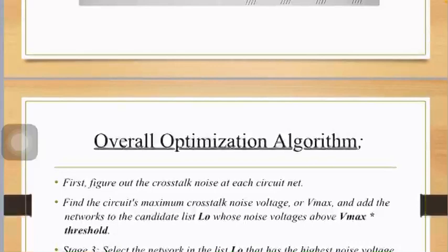A small summary is: first, each crosstalk voltage is recognized at each segment of the circuit. Then a graph is plotted where there is more convergence. That convergence is reduced by adding suitable transistor gate sizings and logical gates, which repel the crosstalk noise and allow the sound signals or any kind of data signals to flow through the transmission lines to the receiver without any interruptions.